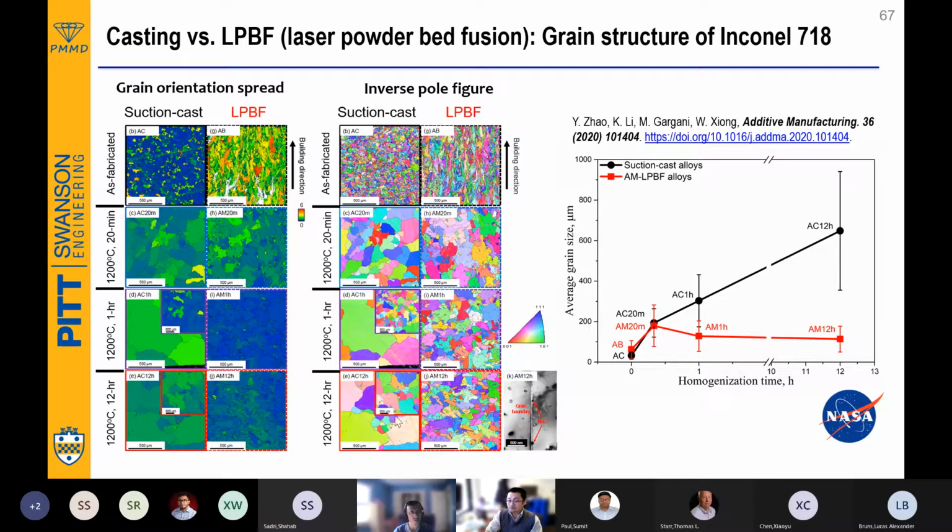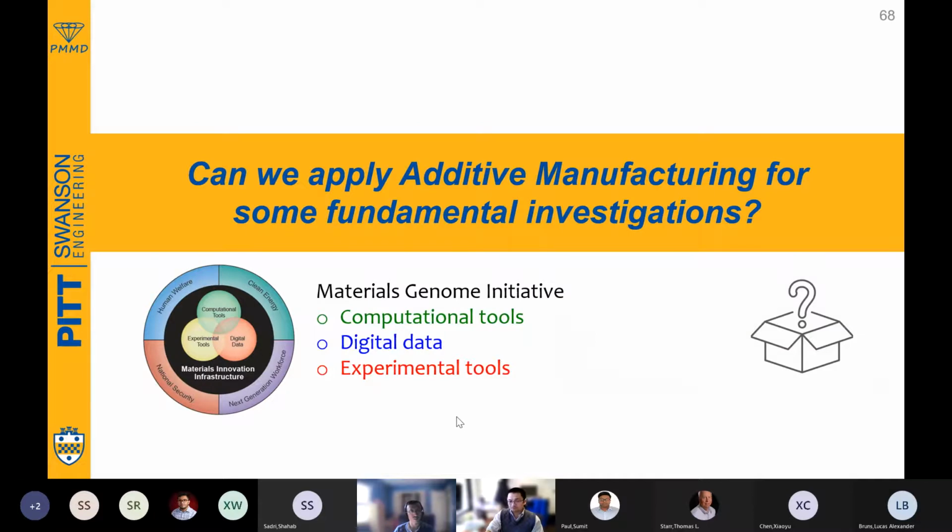The reason is because the additive manufacturing actually, in the as printed microstructure, we bring a lot of residual stress. This residual stress is not necessarily forming the crack, but is high enough as a stored energy to trigger the recrystallization. So if you choose the proper homogenization temperature, then you can use recrystallization to refine the grains. So that's kind of striking, and we feel so encouraged because additive manufacturing is not just a toy. You can get better configuration of the grain compared with traditional manufacturing processes.